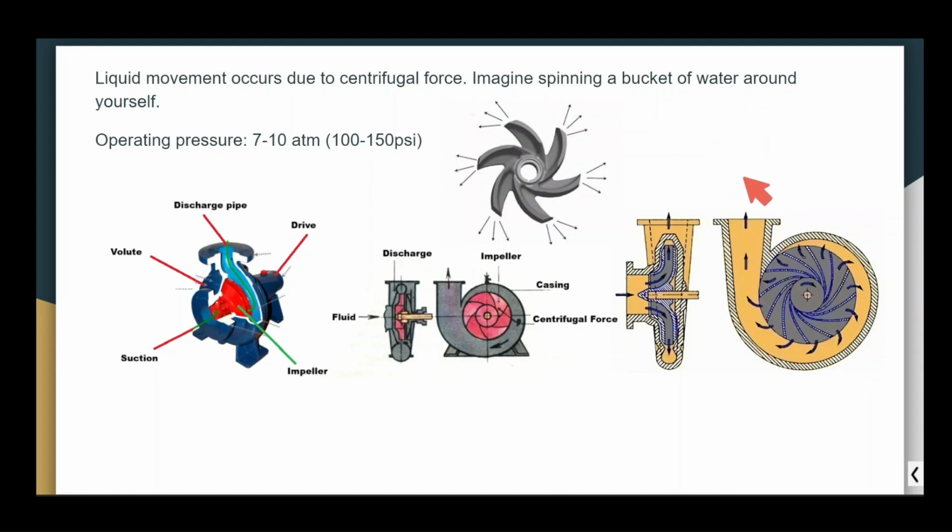the discharge, to the upper manifold. This is the impeller. These arrows show how the centrifugal force is directed. If we close this system, we can direct the fluid to a specific place. In this section, there is a vacuum effect in the center of the impeller.